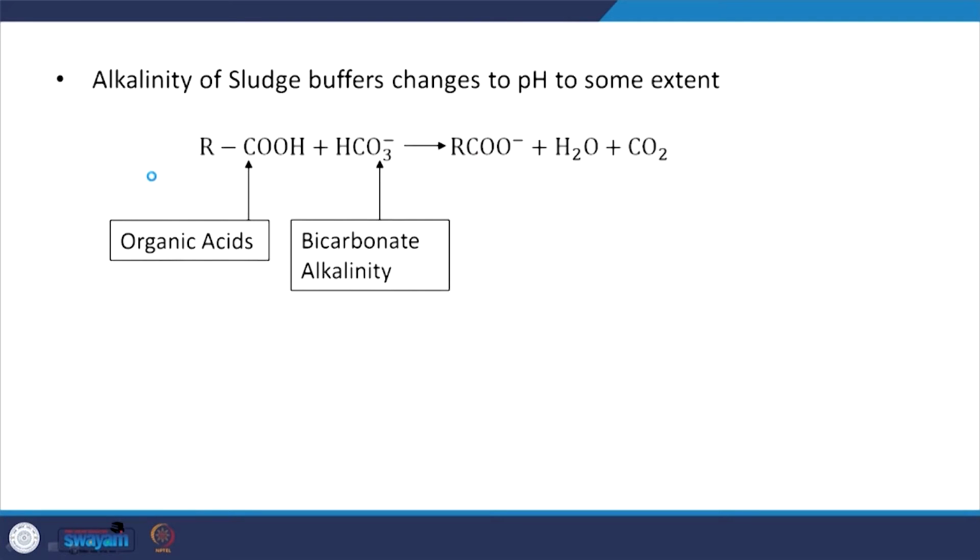So, we looked at the relevant aspects and we were looking at alkalinity and why that is necessary. We can see that we are going to have acetic acid being formed typically, CH3COOH, acetic acid. Acetogenesis was one of the steps in anaerobic digestion, right. First hydrolysis, and then you had acidogenesis, where you have the intermediate volatile fatty acids typically being formed, and then you have the acetogenesis, acetic acid being formed, and depending upon the type of the parent compound, you will also have hydrogen being formed, right.